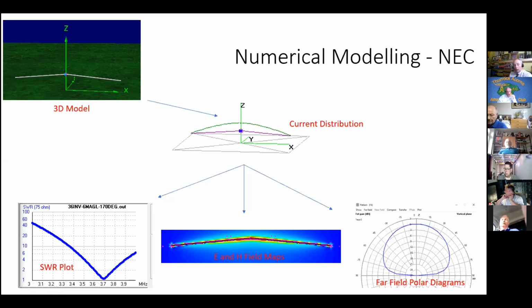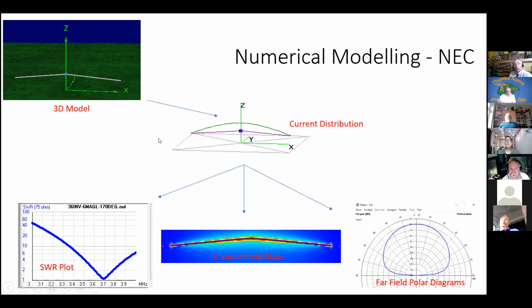You will hear of things called MMANA-GAL and ESNEC. They use the NEC core software, but charge license fees for what they have built around it, whereas 4NEC2 is completely free. ESNEC will do very simple antennas with the free version. MMANA-GAL will do complex antennas, but won't do near field plots unless you pay the authors for an add-on module.